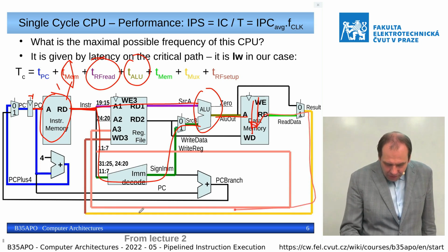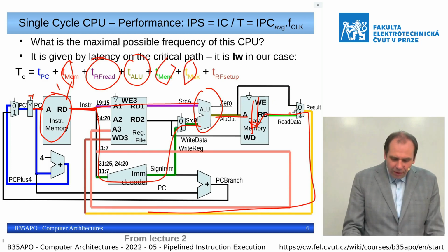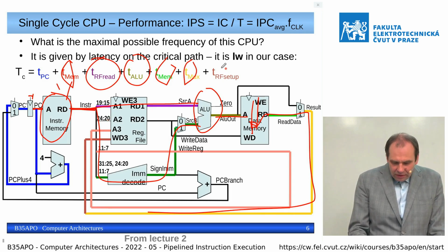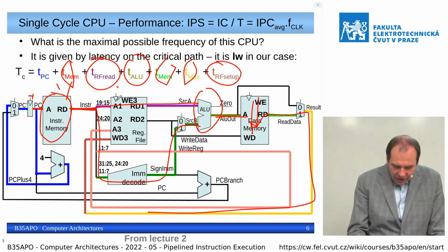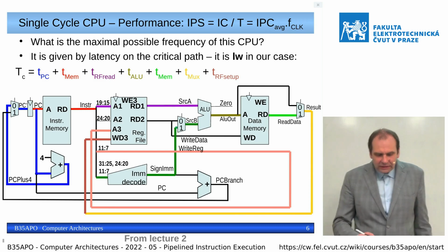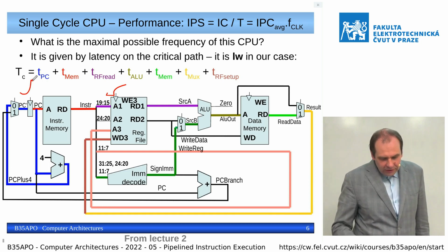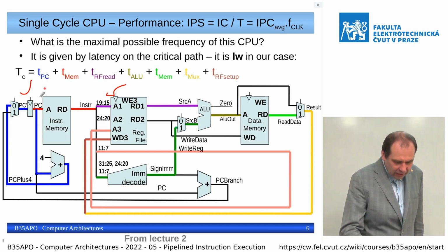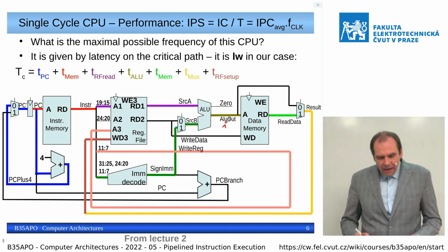And then we need to provide some time to select the correct output, if it is bypass or memory, and with some time reserved for the register file to store the value, we need to provide a stable value here before we advance the CPU to the next clock cycle by the next positive edge on the clock signal. And at that clock signal, again, we get a new address of the new instruction, and the main CPU cycle can continue. But it is a problem.